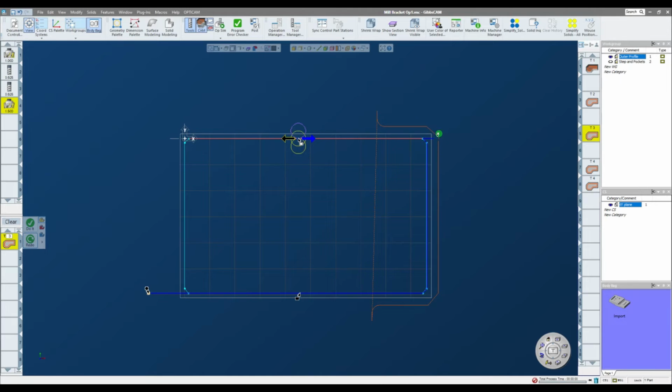Now say I only wanted to do two sides, I would have to take my white square and drop it on this line here. Then if I did a redo, it would start where this one is, and I could extend the toolpath up in this direction. So that's essentially how markers work. They dictate the start and stop geometry for the toolpath, and the circles extend the toolpath. Now with a closed shape, it's all going to start and stop at the same point by default.